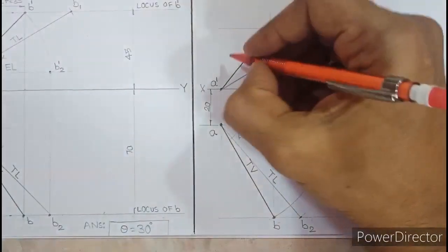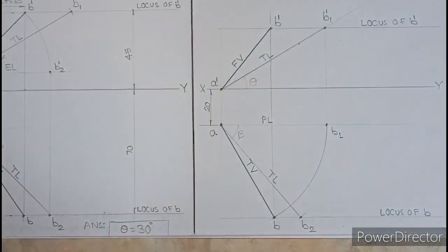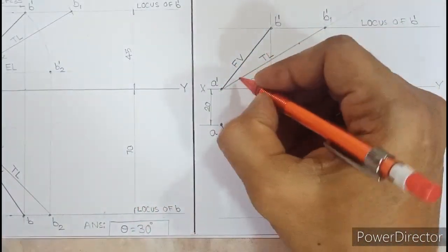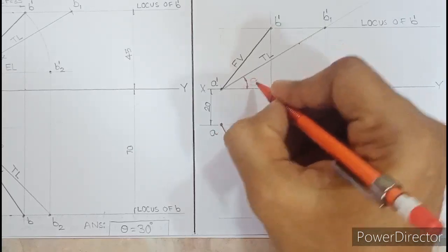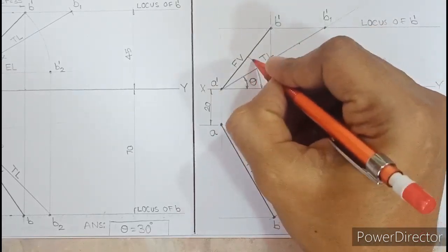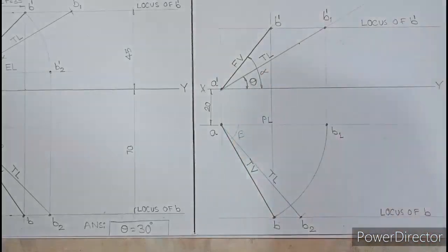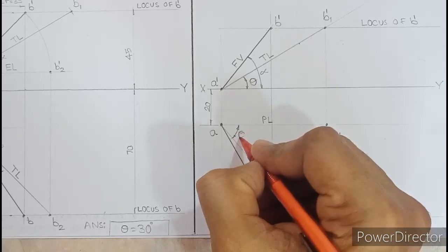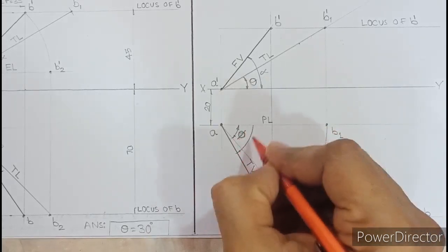After I draw this dark, above the line, along the line, write FV, meaning front view. So that is how this is called draw projections. Last but not the least, show angular. Show means you have to specify the angles. So this is theta, do not write the value. This angle is alpha. Theta and alpha are best friends, always together. The inner angle is phi, what they've asked you to find. And the outer angle is beta.